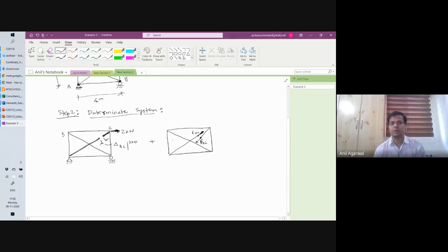What I have done here is I have cut a member. If the redundancy was of this kind, which I could handle with a boundary condition, so for example, if the truss problem was this one, you are following me, right? As I had mentioned before, the redundancy that I had to remove was simply this boundary condition, and I would have applied an external force. Just like I did in the previous example, I removed some boundary condition and I applied the corresponding unknown force or redundant force. Correct? But in this case, the redundancy is not coming from a boundary condition.